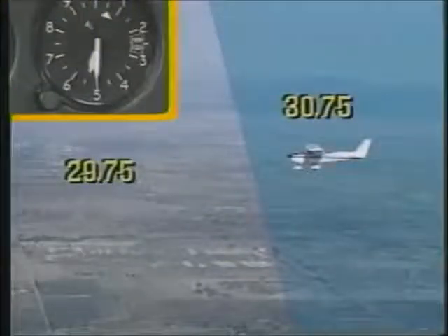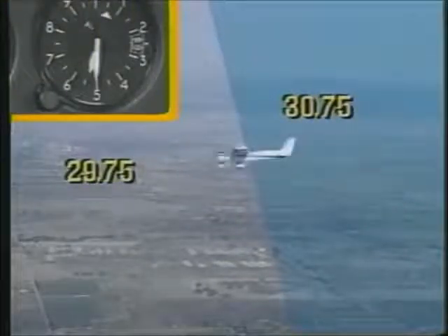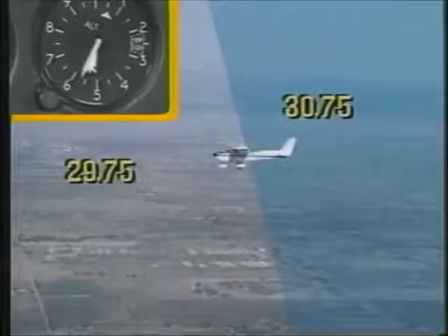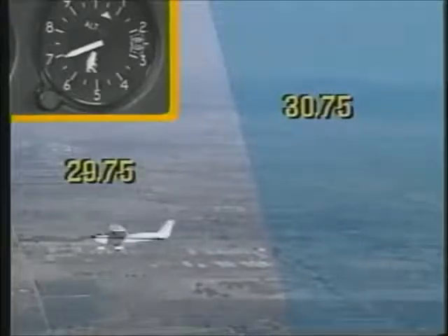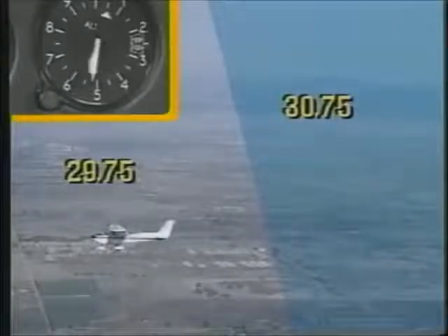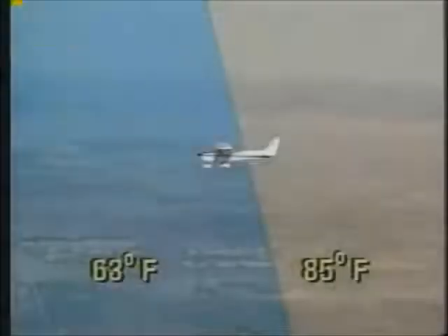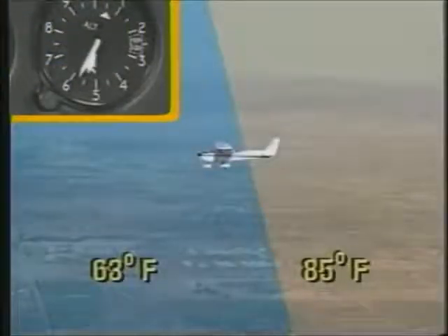Suppose you're maintaining an altitude of 5,500 feet, and you're flying into an area of lower pressure. The altimeter interprets the decreasing pressure entering the static port as a climb, although you're actually flying level. When you notice the altitude gain, you will naturally lower the nose to descend to your desired altitude. However, in this situation, you will actually be descending to a lower altitude, even though the altimeter shows a return to 5,500 feet. To a certain degree, the same situation occurs when you're flying from an area of warmer air to one with cooler air.